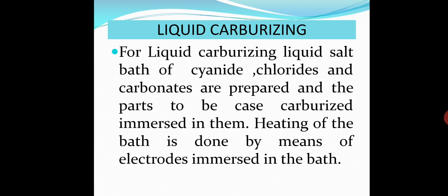Next is liquid carburizing. For liquid carburizing, a liquid salt bath of cyanide, chloride and carbonates is prepared, and the parts to be case carburized are immersed in it.